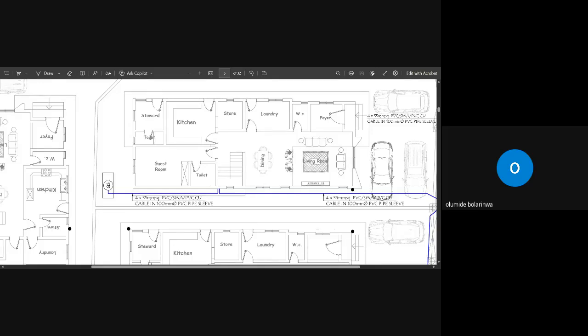The distance between your wall and where your changeover is, we allow 2 meters. So extension is 2 meters, projection to where your changeover is 2.4, and termination is 600 mm. Do you understand me?